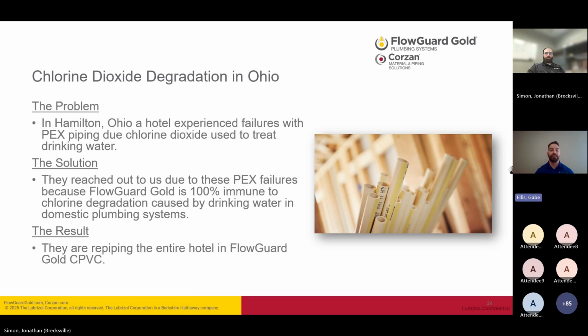Actually, the city's executive director of infrastructure said, we've got about 21 miles of HDPE piping in our system now, and it has catastrophically failed almost 60 years ahead of when it should have. So this backs us up about 20 years ago with the future attack on water mains. And unfortunately, the chemicals we use attack the pipes and then cause them to fail. So that's what's happening in cold water systems. Imagine what can happen in hot water lines with additional pressure.